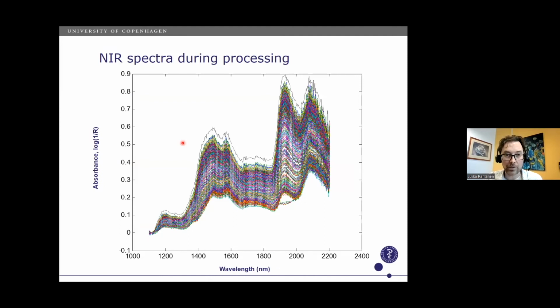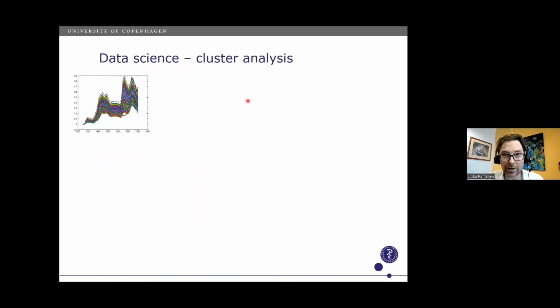And then this is a result of a typical granulation. So what we can see is a mixing of powder in the beginning, followed by an increase in the water absorbance when we are increasing the aqueous granulation liquid. And then each measurement takes a few milliseconds. So we can collect thousands of spectra while we are processing. And this is an area where you then start needing multivariate analytical tools. So you might have heard about chemometrics. So chemometrics is commonly used for analyzing these data sets.